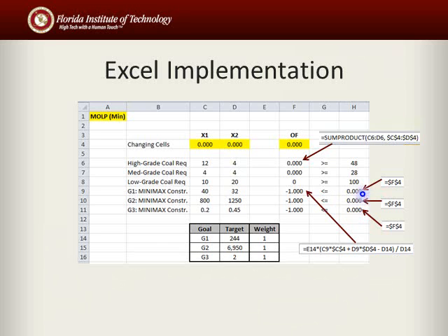It's going to find the maximum deviation possible for each of these 3 constraints, and our objective is to minimize that maximum deviation. It's pretty cool that this objective function cell is both a variable cell, because these all call upon that, since these are all F4, and at the same time, it's an objective cell as well.